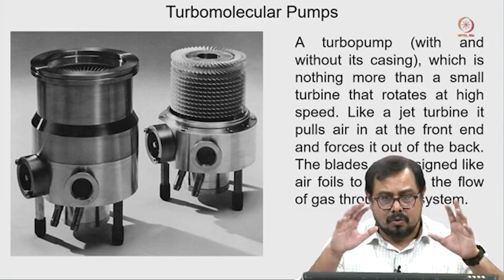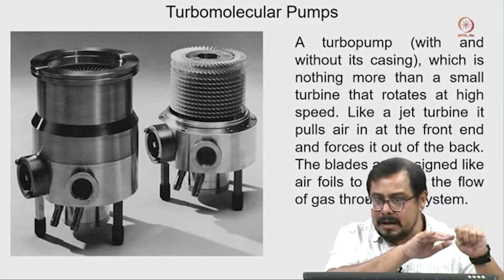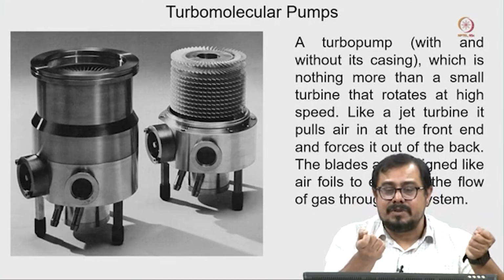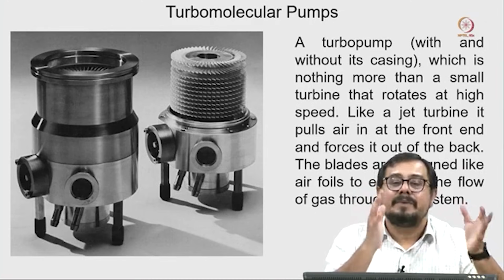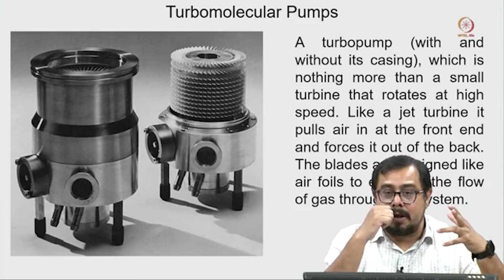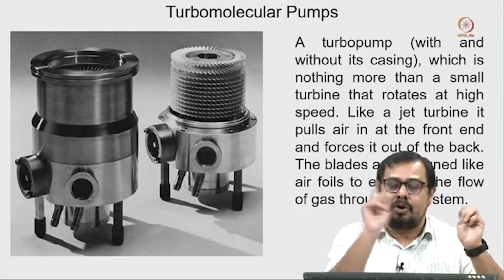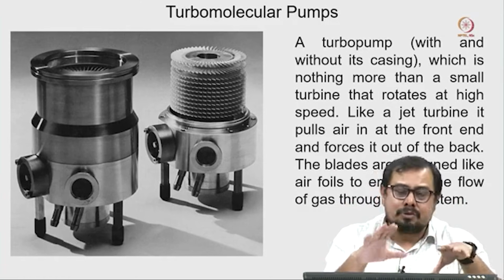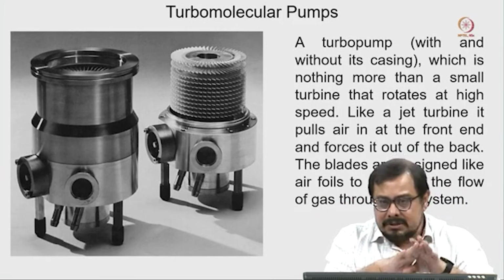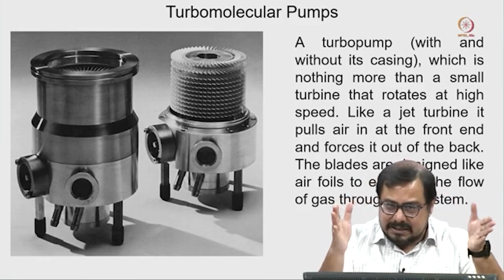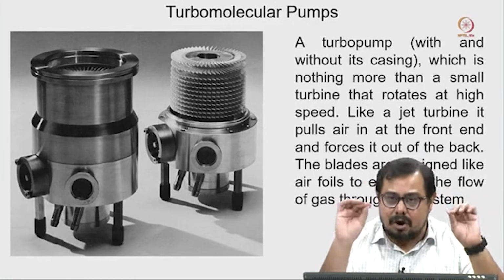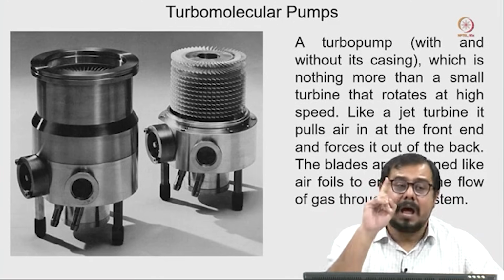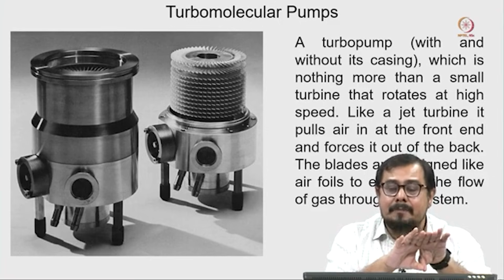So, that is a good setup, going from atmospheric pressure to a very high vacuum, but the drawback of this pump is that it is a very noisy pump. Because the turbine rotates, it generates noise and vibration, and that is going to affect our imaging. That is one of the reasons we use this pump only until a certain high vacuum is reached, and then it stops automatically, and we switch to a different type of pump, called the ion pump, and that pump works in a very